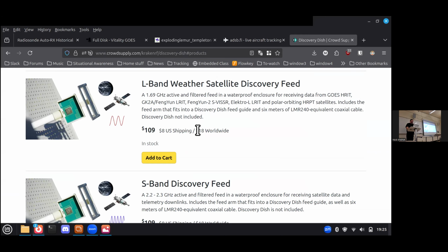If you want to stick with the grid antennas, so you have one of the grid antennas. What frequency is the feed made for? Is it a 2.4 gig, 1.9, or 1.7 gig? We tried making one for 2.4. Oh, no, yeah, we made one for 1.9. But we tried the 2.4 originally, and it didn't work at all. Yeah. 1.9 will work, 1.7 would be better, but it's hard to find the 1.7 gig feeds.